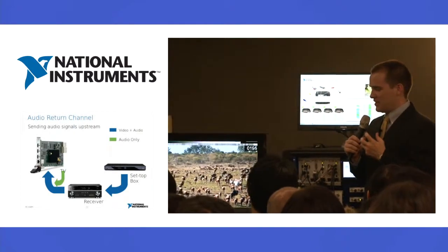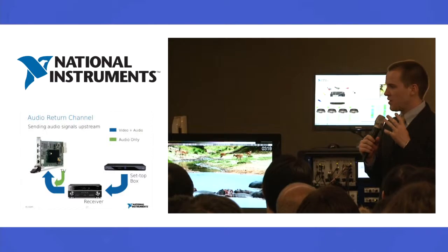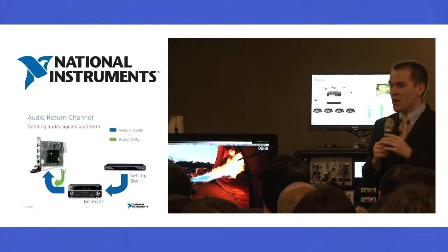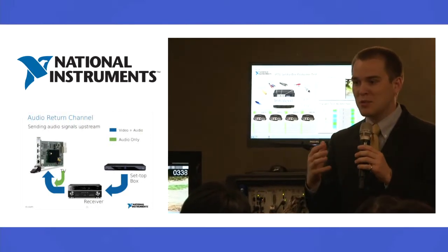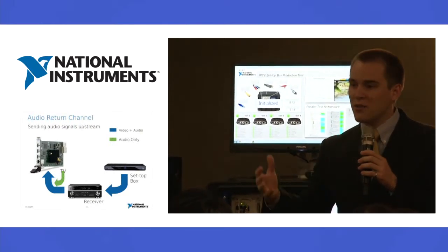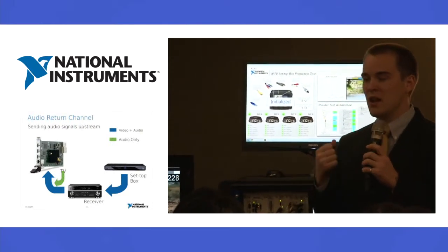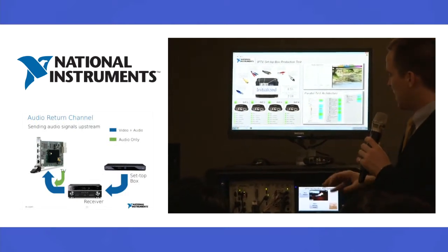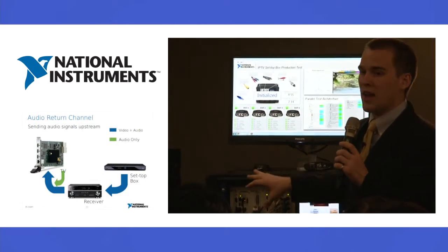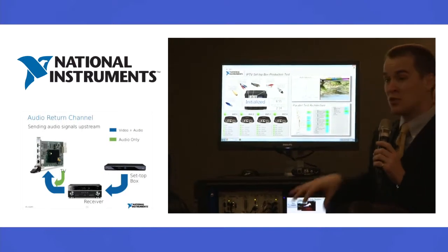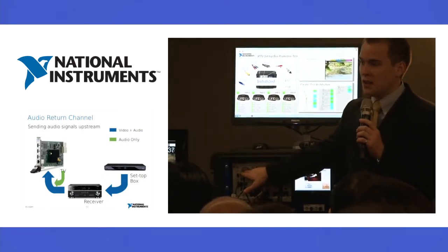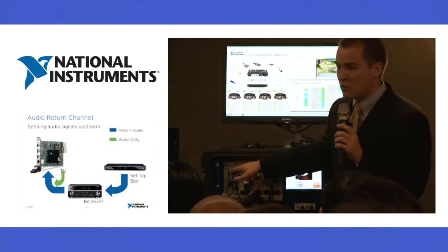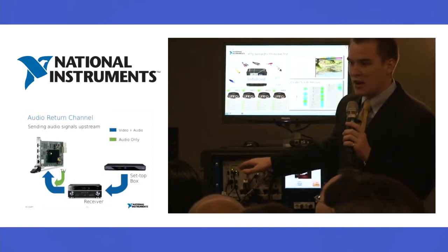PXI is this really revolutionary test platform. It is based on PCI technology, PCI and PCI Express, the same stuff that's in your computer. So it's a very, very high throughput, low latency, great platform, and this box leverages all of that technology, but for instrumentation. So over on the left side, we have a controller. This has a processor, RAM, a hard drive, and this is a very high-end one.